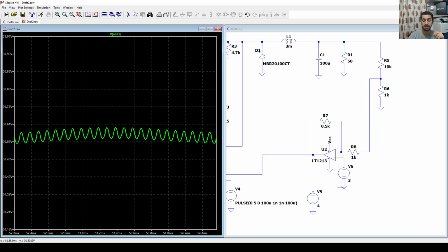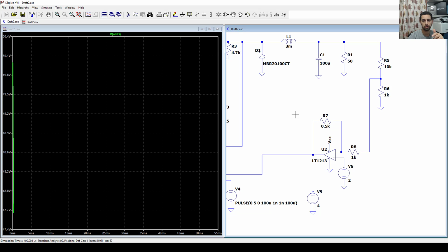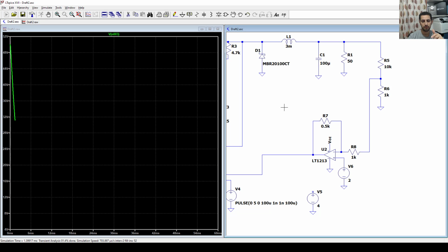So maybe you can assume that okay, you want a little bit of I controller here, and that makes it better. Okay, so if I want now to get a different voltage, for example 20, I set this to 2 and it should go to 20. So I will see if there is a big steady state error, because PI control removes the steady state error, and I will leave it to you if you want to add PI control and how to use an operational amplifier to implement PI control. It's going near to 20. I assume it will be 20 something, but let's see now.